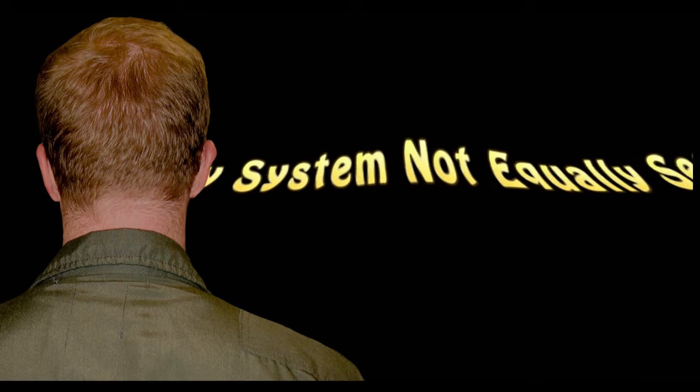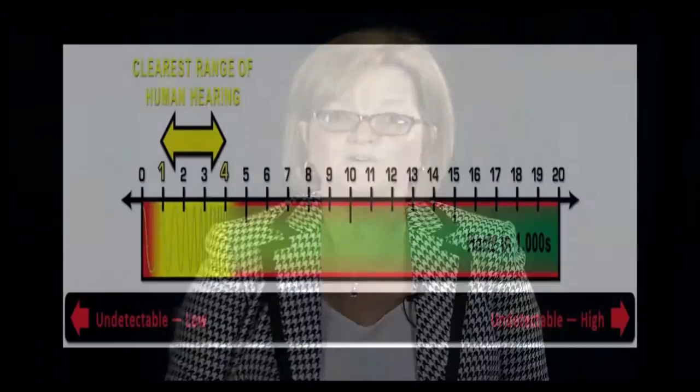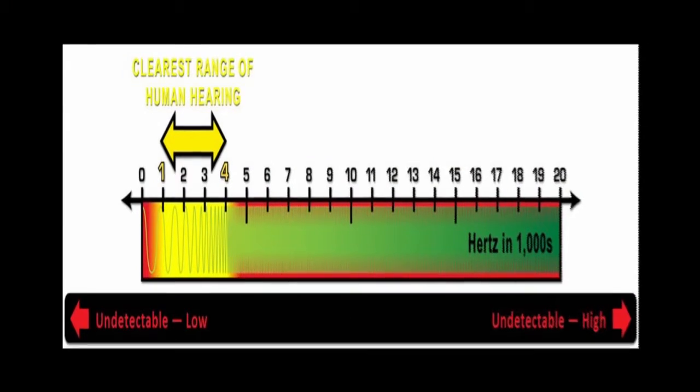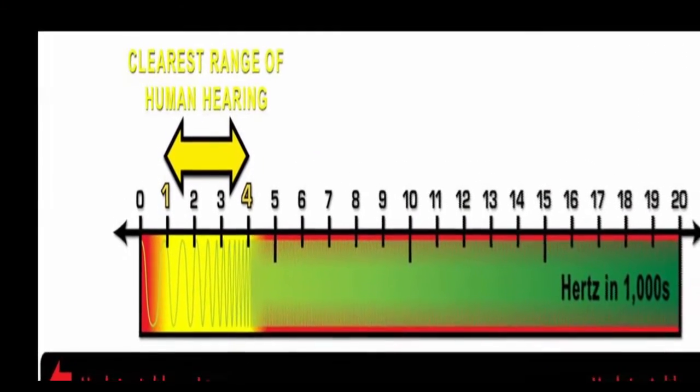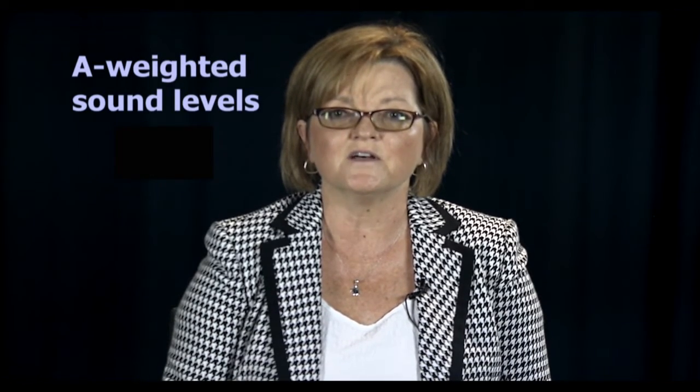The human auditory system is not equally sensitive to all frequencies. While the frequency range of the human ear goes from 20 to 20,000 cycles or hertz per second, we hear best in the range of 1,000 to 4,000 hertz. For environmental analysis, we need a way to measure the same way the ear hears it. The A-weighted sound level achieves this goal. Sound levels are measured using A-weighting, called A-weighted sound levels, and often denoted as dBA.